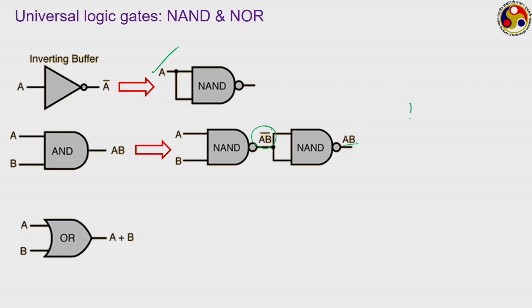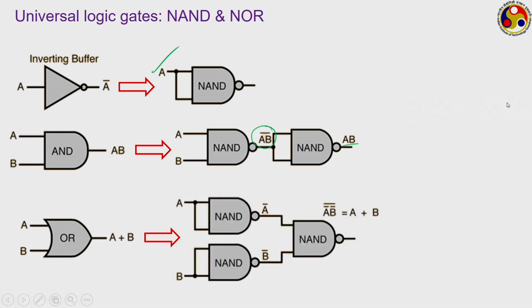Like suppose your A is 1 and B is 0. So via the NAND operation you are getting 1 as the output, and then we are reversing that, getting a 0. It's done, the AND operation done. Similarly, we can get an OR operation done combining 3 different NAND gates. The first one is having A as the input in both inputs, giving A bar. Second one, B is connected to both the input lines of this second one, giving B bar. Now A bar and B bar are supplied to a NAND, and that is leading to your OR operation.